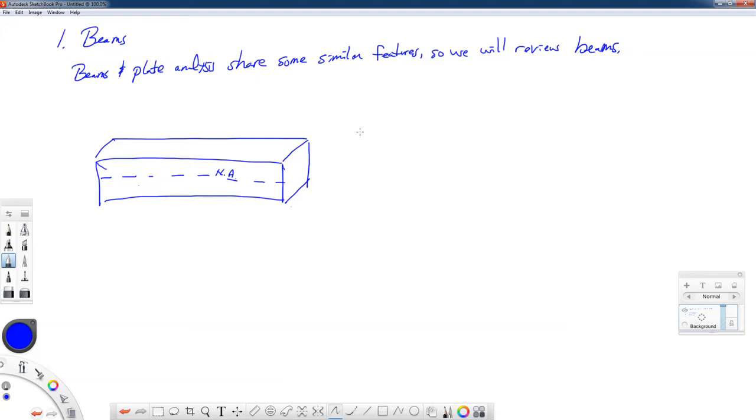And that's something that we go through and we show how that works in mechanics of materials. Our coordinate system is going to be located then at the neutral axis, and for elastic material behavior corresponding to the centroid, we'll have the x-axis down this way. We're going to take the y-axis this way, and the z-axis will be down in this direction.